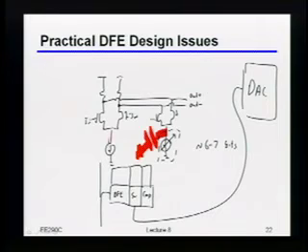So in fact, even this tail current source, if that ends up being big enough compared to your core high-speed devices, you may even throw that out of your high-speed path and just route that tail. It does mean you're giving up some differential noise, or rather common mode noise immunity. But oftentimes, if you're careful about it, that may actually be the more optimal solution from an overall power and feasibility standpoint.